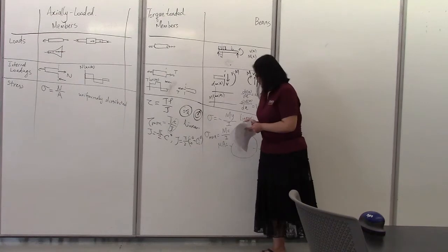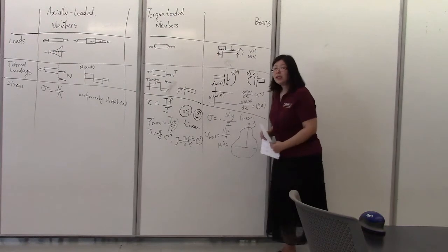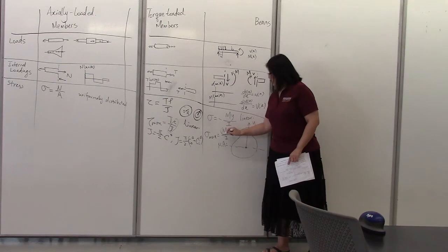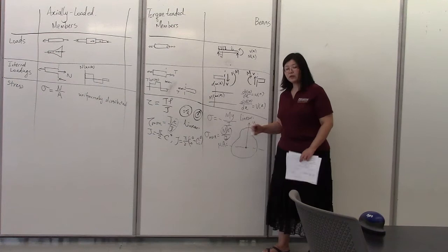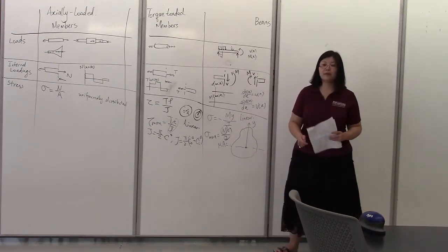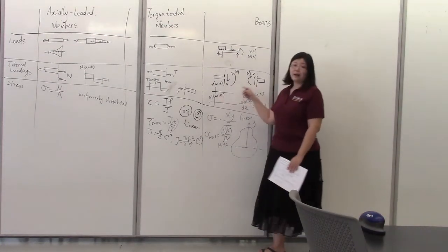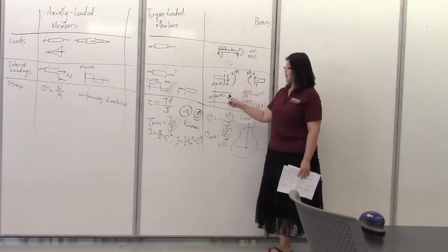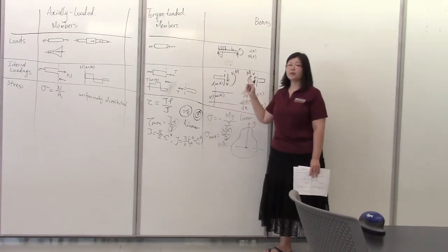Now, when we need to find the maximum bending stress across the entire beam, then again, it's really a combination of m and this product, m times the ratio of c over I. So wherever you have the maximum product, that's where you're going to have the maximum bending stress. If the bending moment has the same sign everywhere, so it's positive everywhere, then you just need to look at the specific cross-section that has the largest m. Then the maximum bending stress will definitely occur on that specific cross-section.